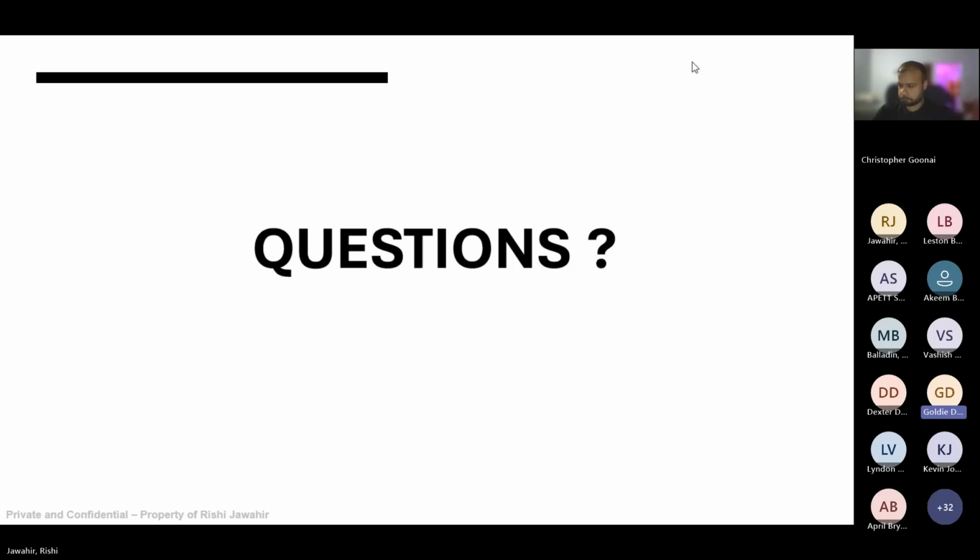I just wanted you to recall for me, please, the four major components of bearing analysis. The first one is the four major components, the four defect frequencies, and what are the other two? Right. So the four major components would be inner race, outer race, the element, and the cage. The other one will be the defect frequencies associated with those parts of the bearings, right? So you'll have a defect frequency of the inner race, outer race, the element, and the cage. And then there are the four stages of bearing failure: stage 1, stage 2, stage 3, and stage 4.